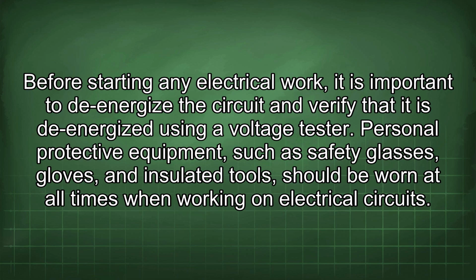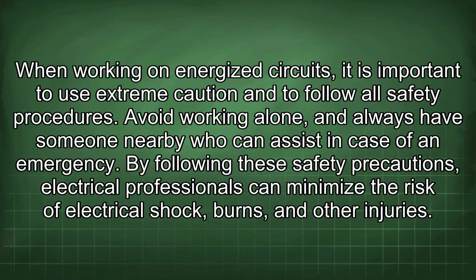Personal protective equipment, such as safety glasses, gloves, and insulated tools, should be worn at all times when working on electrical circuits. When working on energized circuits, it is important to use extreme caution and to follow all safety procedures. Avoid working alone, and always have someone nearby who can assist in case of an emergency. By following these safety precautions, electrical professionals can minimize the risk of electrical shock, burns, and other injuries.